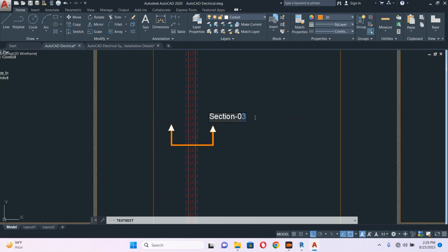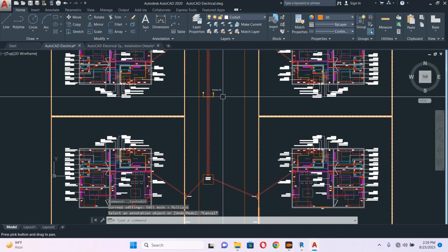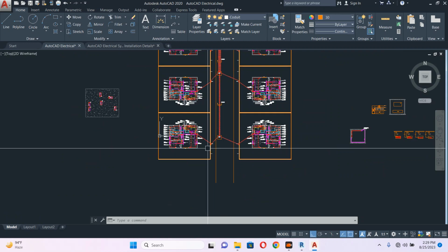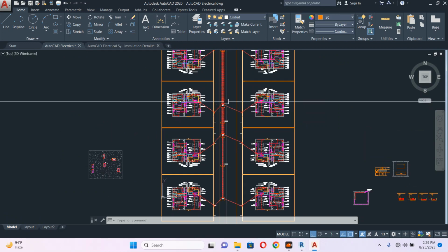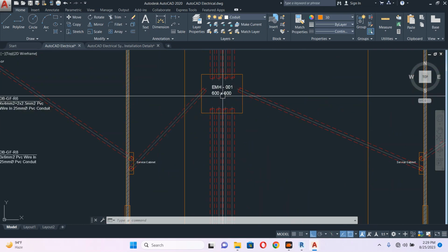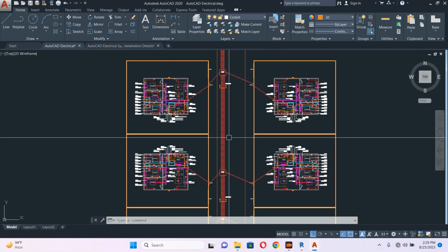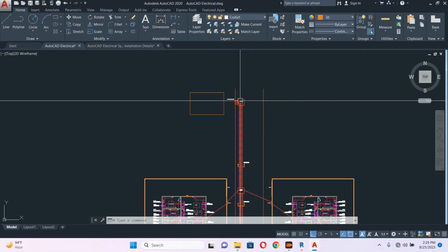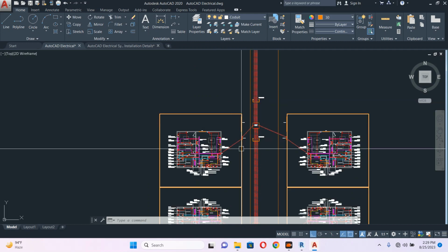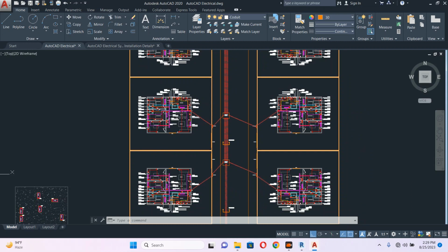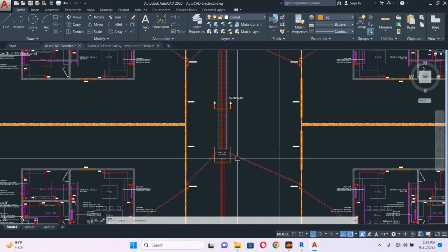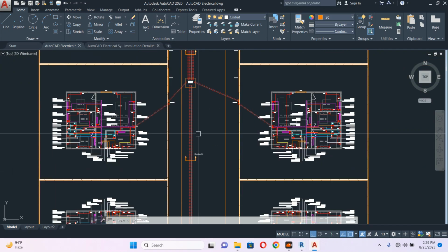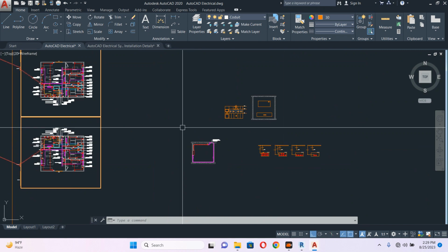End of the duct. So you may ask why we need this manhole. We can connect directly from here. Or you may ask why we need manhole. This is for the service. Otherwise, how can they pull the cable? So from here they will pull the cable up to manhole. From here they will pull here. Then it will go to the house. It's all for the pulling cable, and this one necessary for the service. While you are walking in the road, you will see this manhole. This is very important. So this is, let's make section 1, 2, 3, 4.